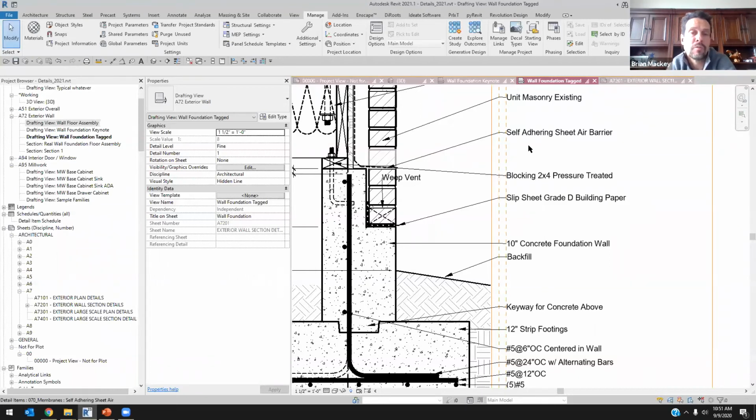I've seen too many clients have too many projects. We find that, oh, this family is causing the corruption. Oh, that family, somebody exploded a DWG inside of it. It's not something that I ever do. So for me, if I'm going to be doing anything with DWGs, I link it in, put it in the view I need it to be in, and I don't explode. I don't try to do anything. It is what it is. And if I bring that detail in more than once, it needs to be converted.